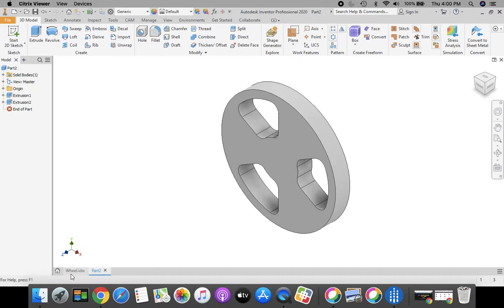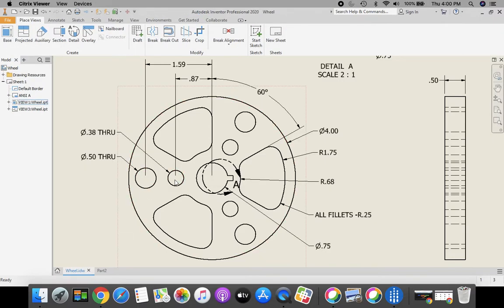Next, we're going to do these holes. There's a 0.38 and a 0.5 diameter hole. Now notice we're going to be working on our 3 o'clock side of the circle. I'm sorry, our 9 o'clock side of the circle. The 3 o'clock side, we had this shape slot over here. Now on the 9 o'clock side, we're going to put these 2 circles and circular pattern them around. 0.38, 0.5.